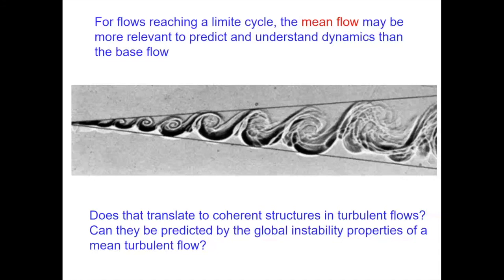Okay, and so the idea is to try to compute the mean flow as being forced not only by the coherent fluctuations, as we did just before at laminar Reynolds number around 500, but to also include this term here, which is actually an eddy viscosity contribution. Okay, and so in the end, we need to couple three things.